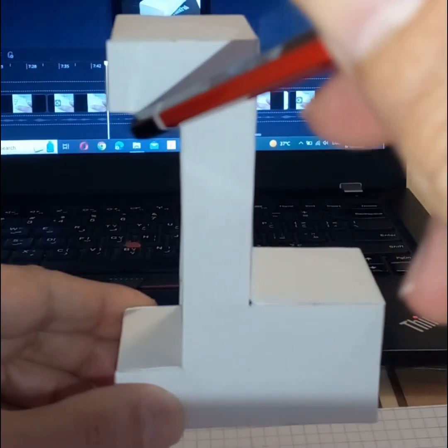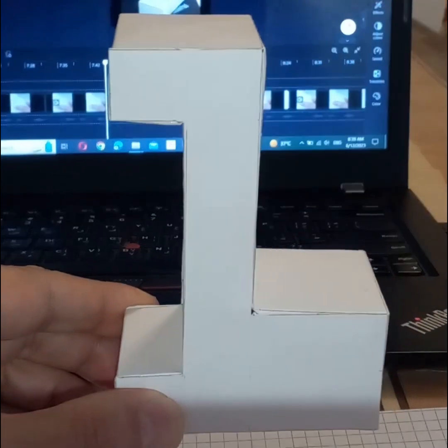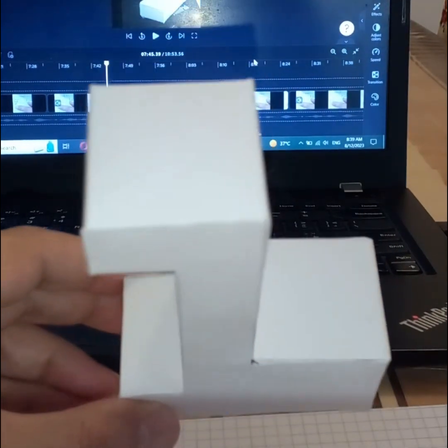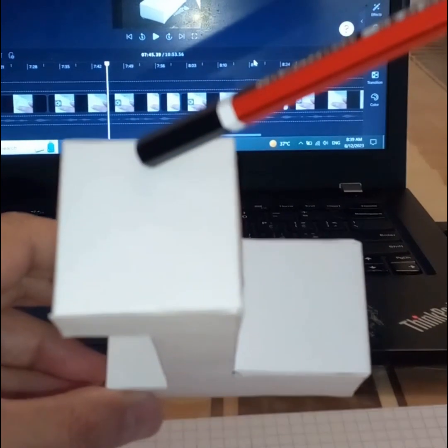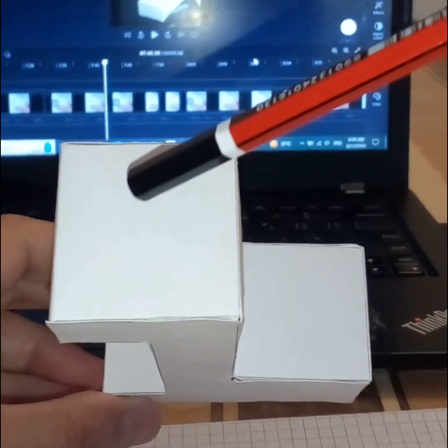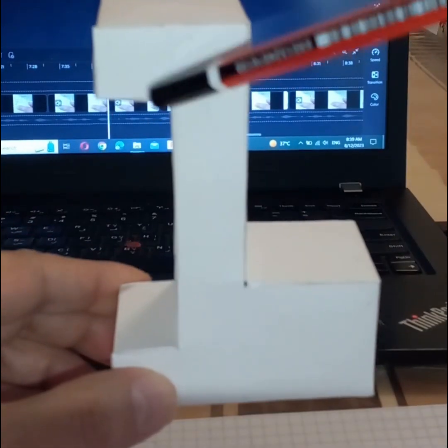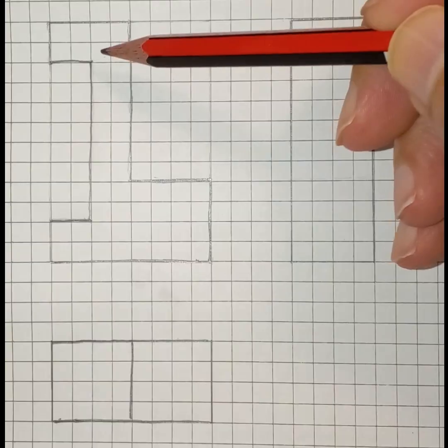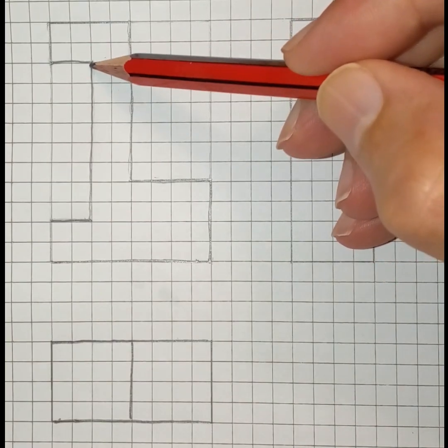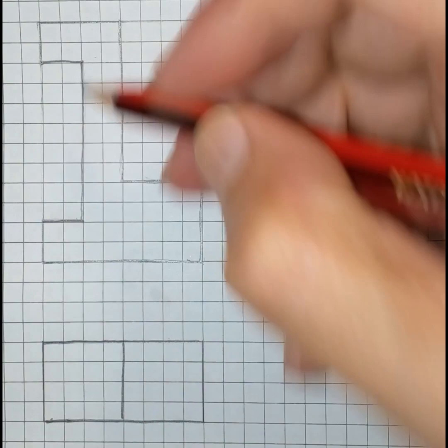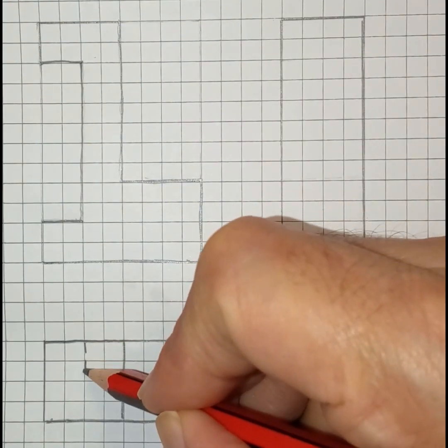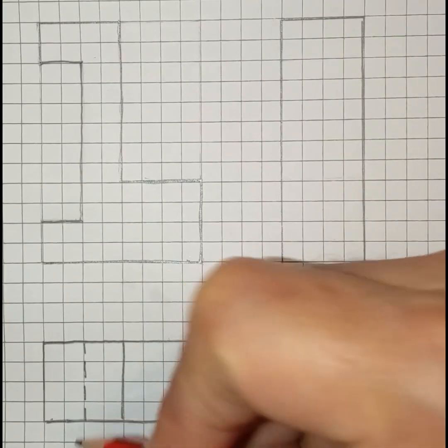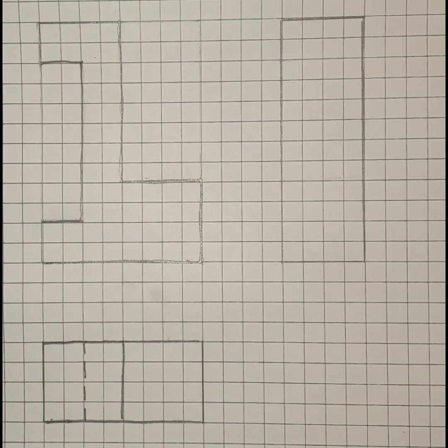As I did in the front view, this distance is 10 millimeter. So in the top view from the left, I will measure 10 millimeter and make a dashed line here, aligned with this line from the front view. The hidden surface is represented by this line in the front view. Aligned with this line, I will draw a dashed line here in the top view representing this hidden surface. So now I finished the top view.